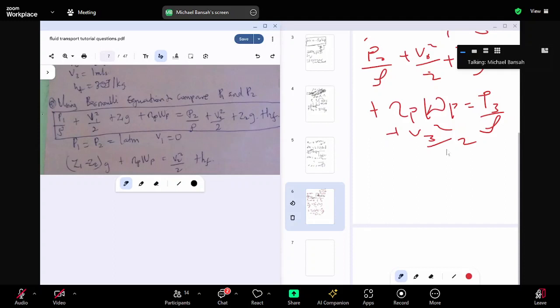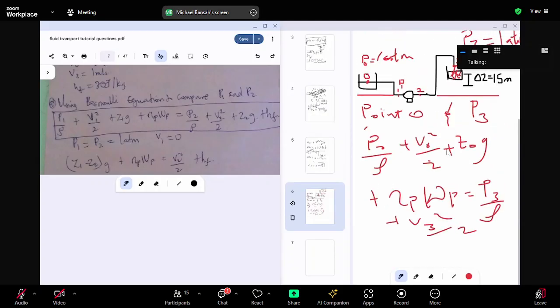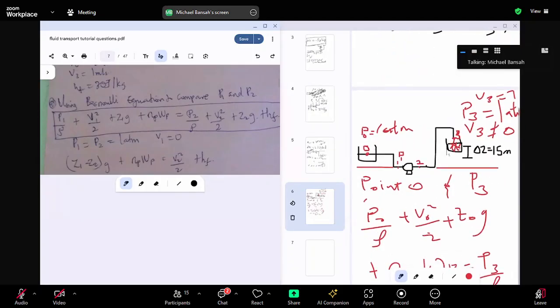All right, so let's use this equation. Following my diagram, I mentioned that at 0, the water is stagnant. So my V1 is 0. Is that fine? Then at the same point 0, my pressure is 1 atm. So it means I have the value for this. Let me use plus for that. I have the value for it. My Z1, that's the elevation at point 1.